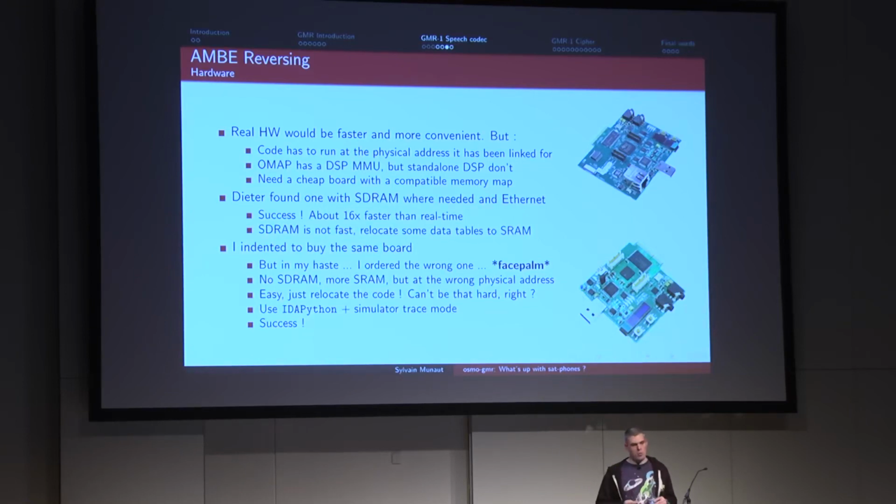Now, it wasn't quite as fast as we wanted, because it was only running about real time at the first try, and that's because SDRAM is slow, especially when you do a bunch of random accesses. And the codec, unfortunately, has a lot of big data tables which are accessed constantly, like to compute cosines and stuff like that.